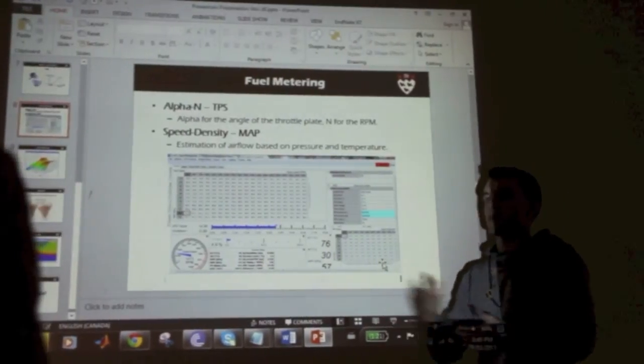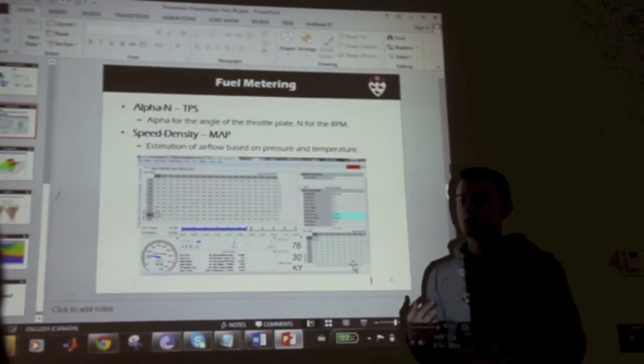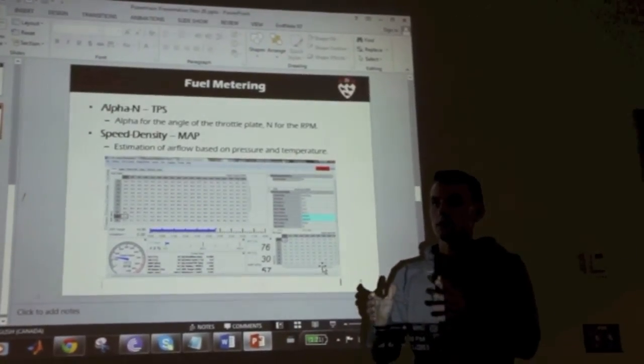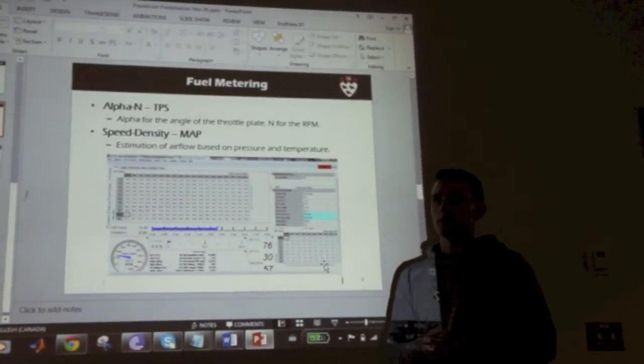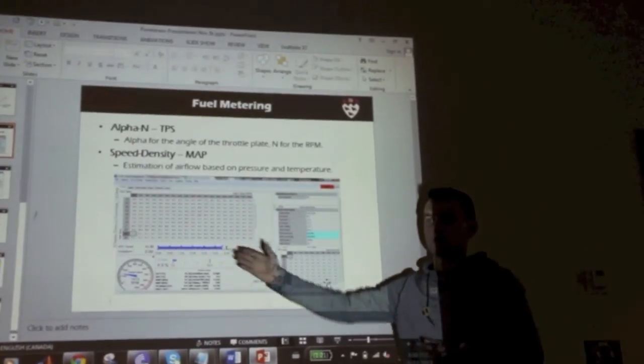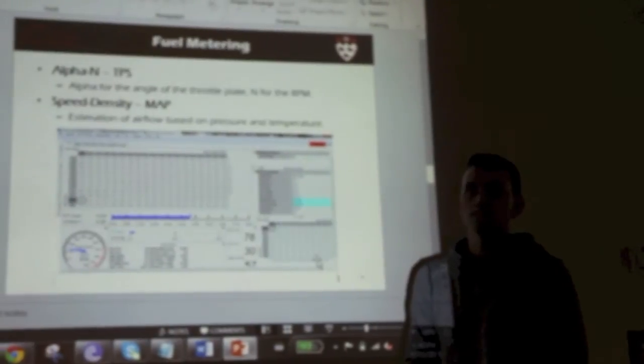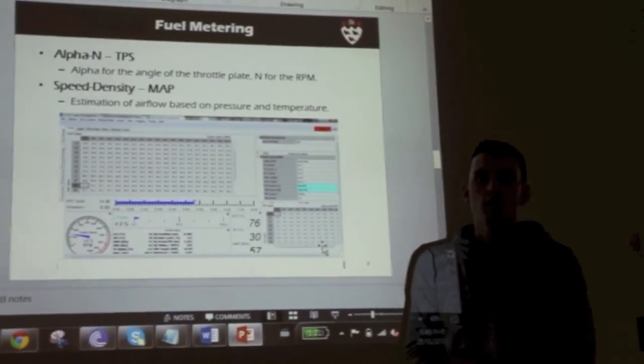Yeah, so the way you accelerate your engine is by removing load. You start off at max load for that condition, and then you slowly pull load off so that the engine will accelerate. How do we do it in the shop? Yeah, it's the same thing.